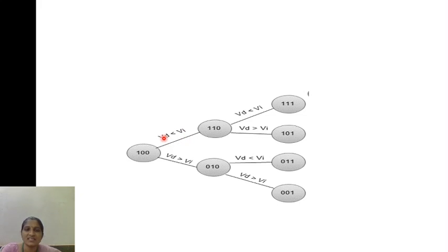If Vi is greater than V0, the output voltage, then what happens is it will keep the MSB bit as it is and it will set the next MSB bit to 1. So the output is 110 now. Likewise, if the input voltage is less than the output voltage, it will make the MSB bit 0 and the next bits as 1 and 0.